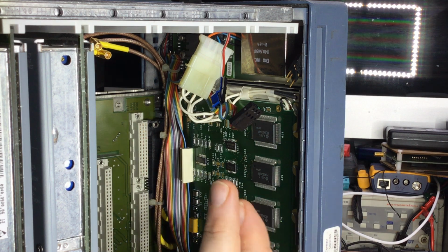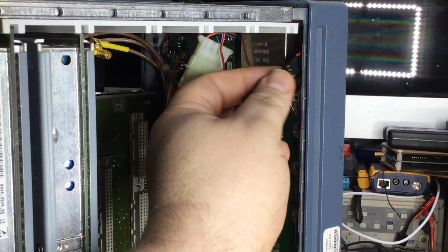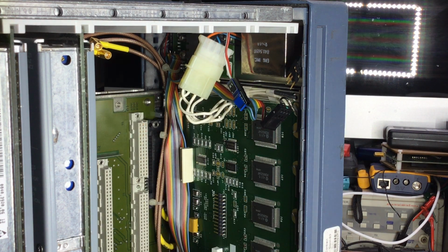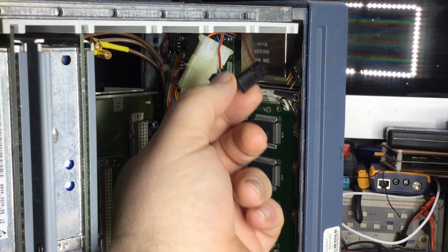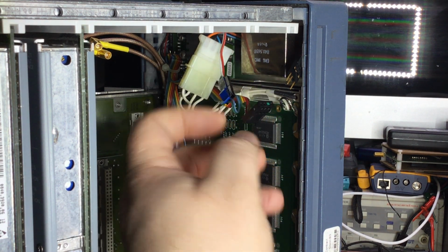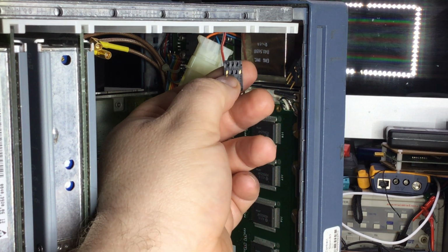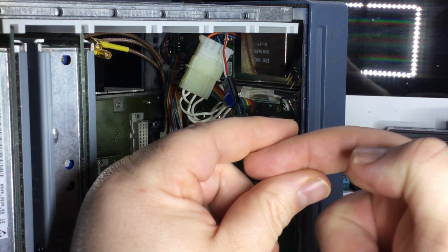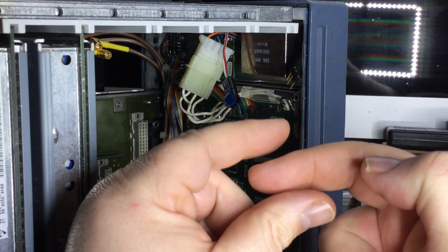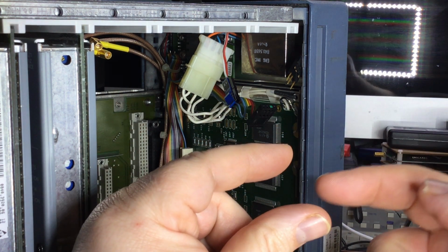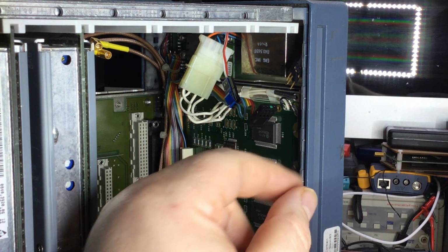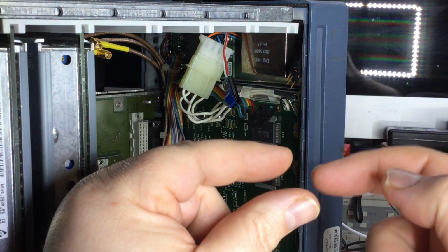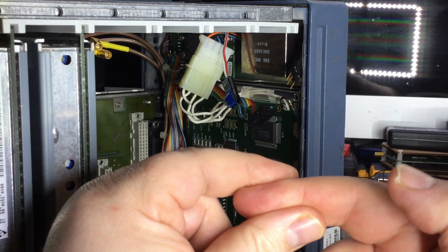So I'm sort of hoping, fingers crossed, that the possible reason for the backlight flickering, in this module that supplies power to the backlight, is because of this having a poor connection. So I probably need to back these pins out, and then because the pin goes in like that, I think the receptacles are too far apart, which is allowing the pin to come out. So I probably need to back the pins out of that socket plug, and then squash the receptacle a bit closer so that it's got more of a grip onto the pin.